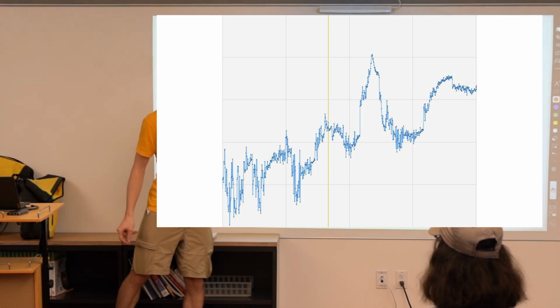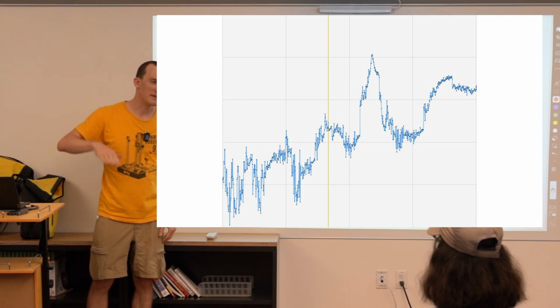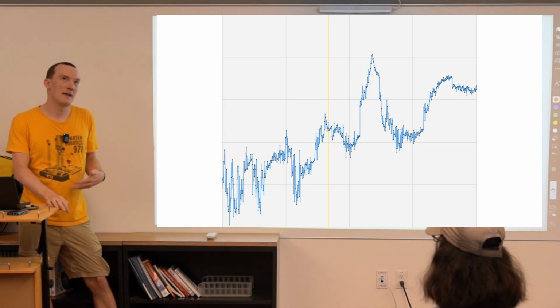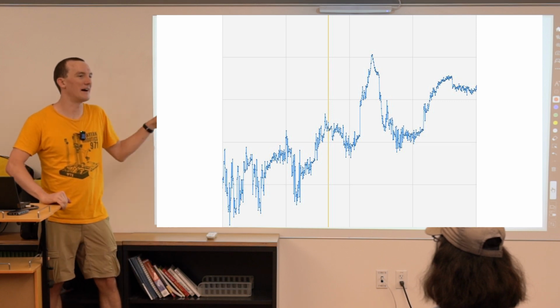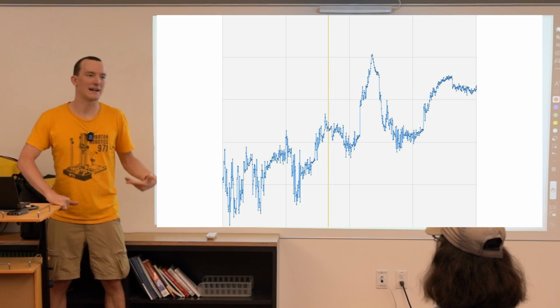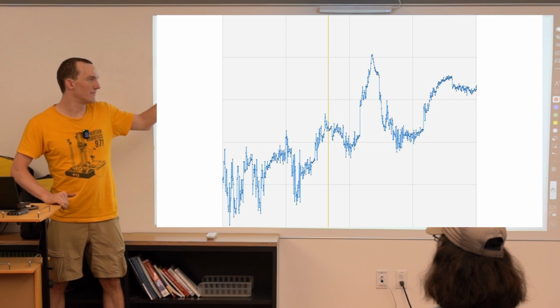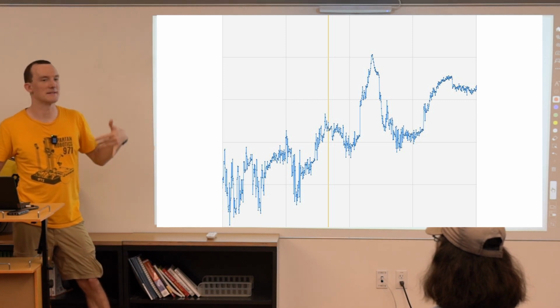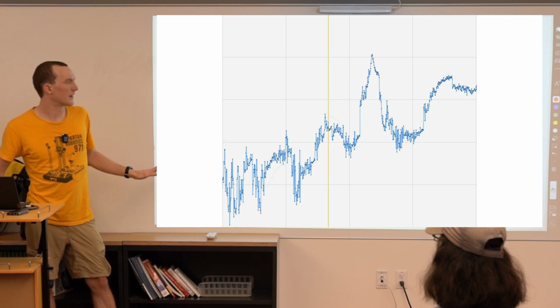And if you try to then control the velocity of a mechanism based on that, you'll be outputting really jagged outputs. And while some simplified models of the world might say, oh yeah, that's fine, it'll just average out in the outputs, in practice, that's not what you want. In practice, if you send those sort of squiggly outputs out, then your robot will not be happy. Your mechanisms will jerk around. It'll not be very precise control. It'll not be great.